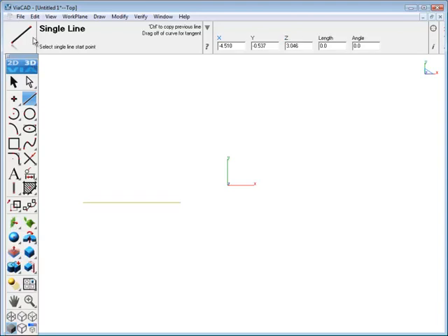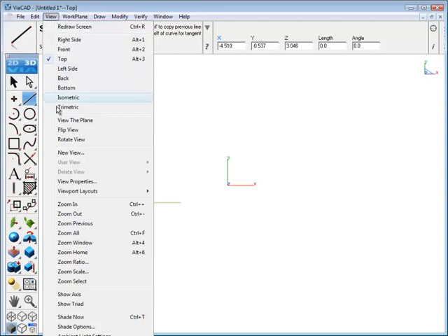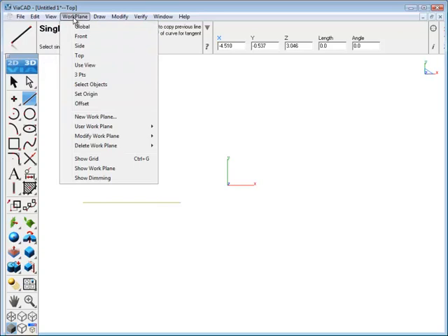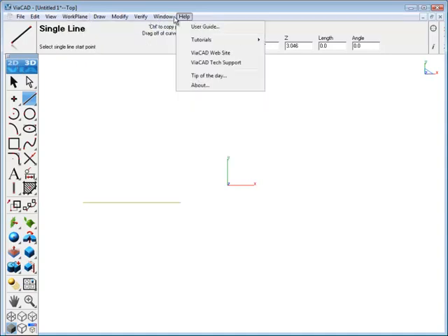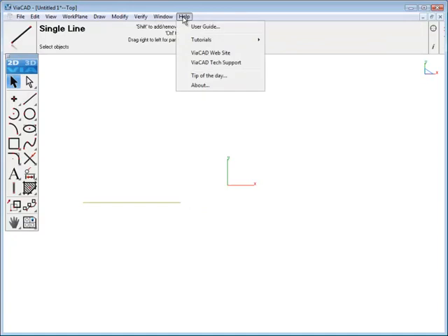In the 3D mode, you'll now see a selection of 3D drawing tools and editing tools. Most important, the addition of the z-coordinate, and 3D views and navigation. Also, availability of work plane choices. Opening and drawing in 2D mode versus 3D will impact the drawing.